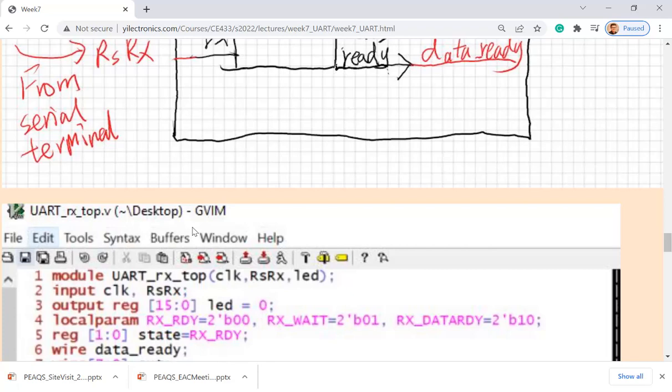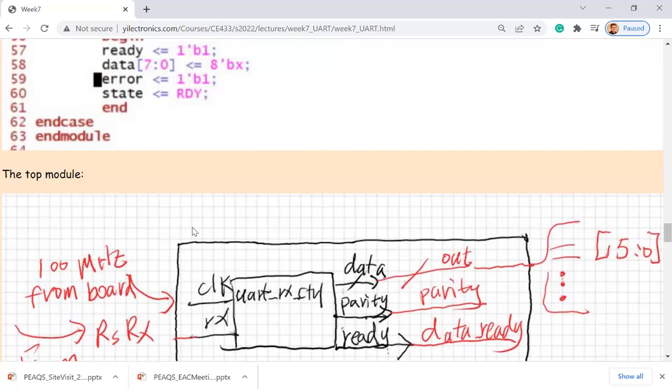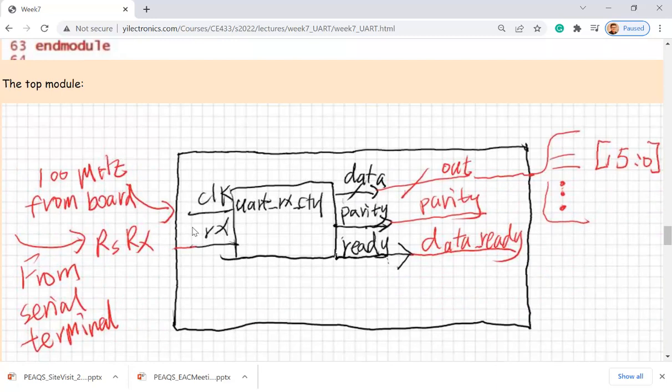The laptop. You have a serial terminal downloaded, and you can even set up an even parity bit in there. So you type A in the terminal, you press send on your keyboard or the laptop. It's going to send that through the USB to your FPGA. So the FPGA is the receiver, and you may have a question: it's a USB cable, why is it UART?